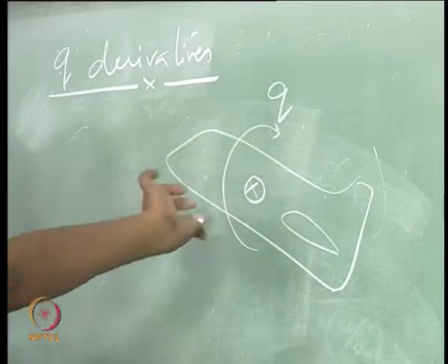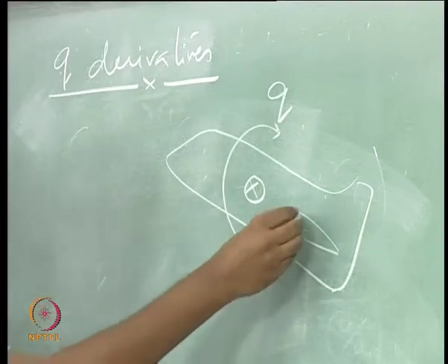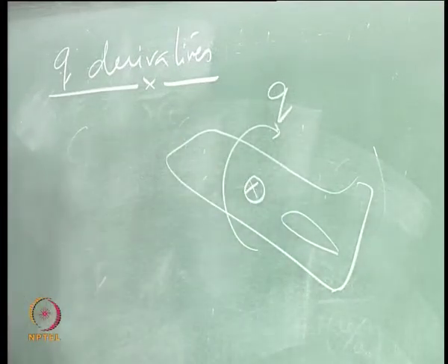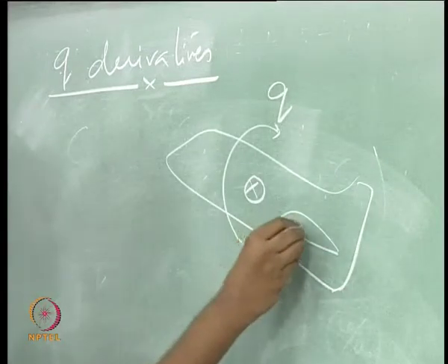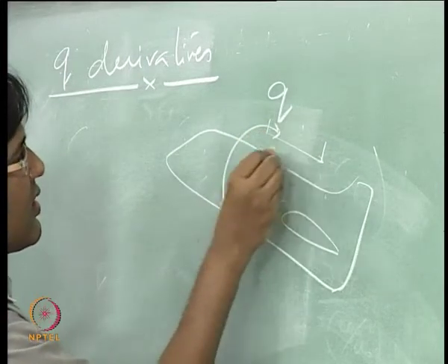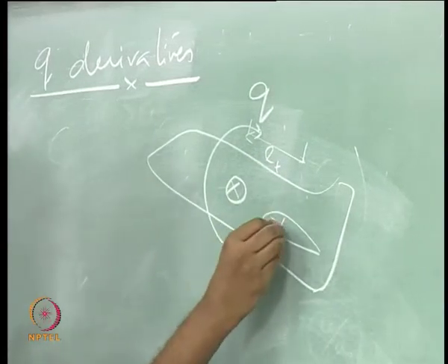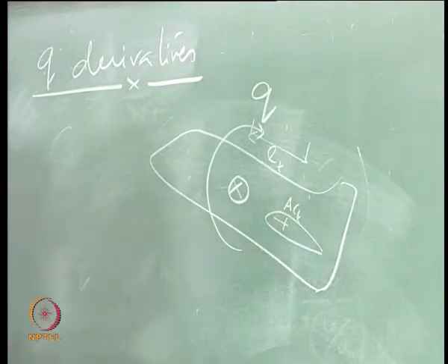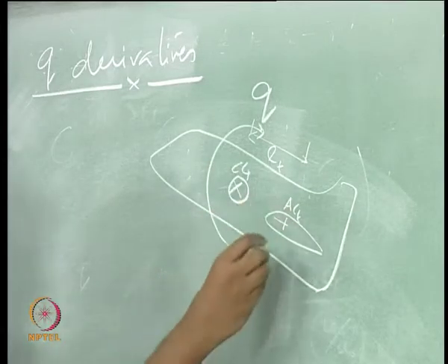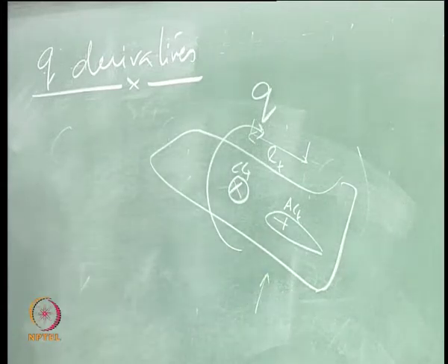So, when you are having a steady pitch up, what is happening? This tail is going down, it is going to push air down, and then you see a relative wind upwards. So, if this distance is LT, then this tail is going to see an upward wind.